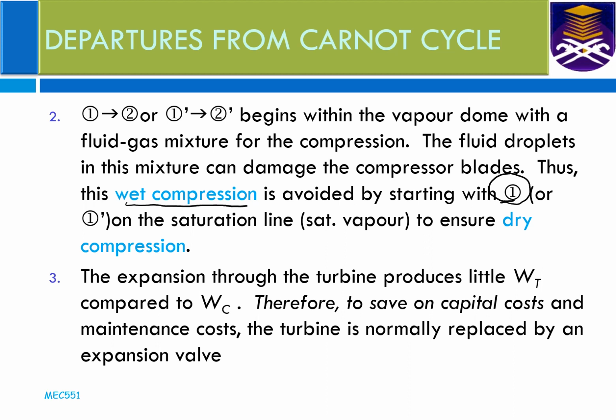That means the fluid must be pure dry vapor when it is compressed in the compressor. Only saturated vapor is acceptable for compression, so the fluid must be ensured to be in dry compression.